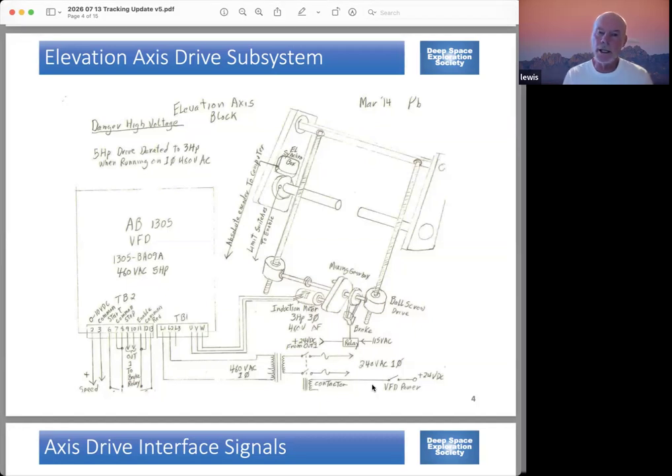And similarly, there's an encoder, a position encoder that's independent of the drive chain. It's the same encoder, same model as on the AS, 16 bits, and there's also a 12-bit encoder. And on the 16-bit, it's routed through Ethernet to the system one. So that's a quick run through of the two axis systems.